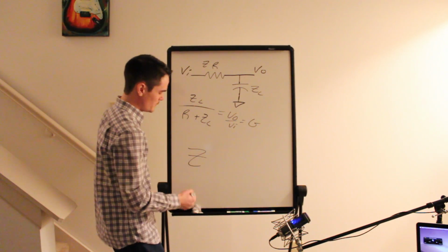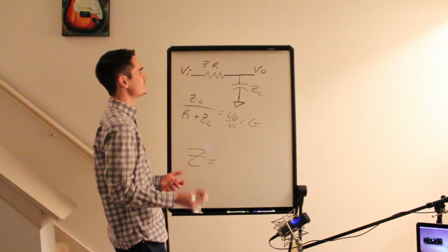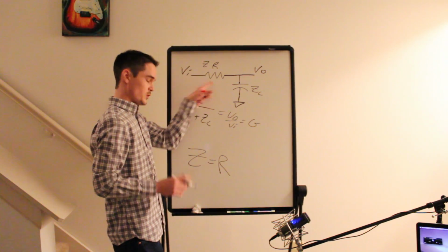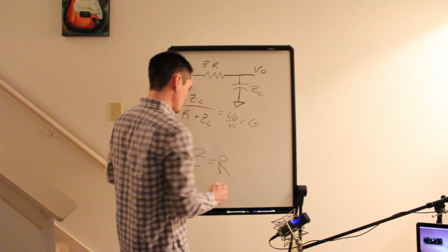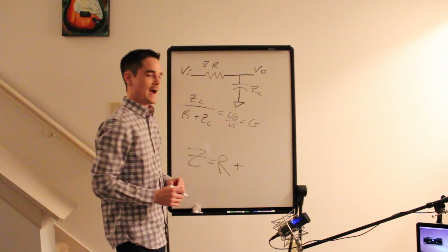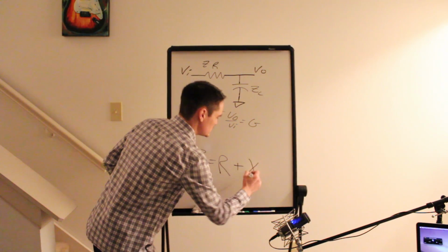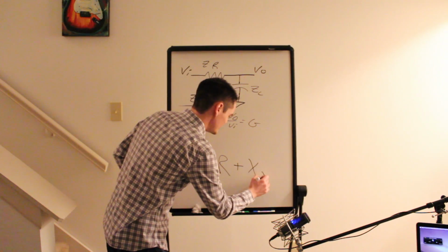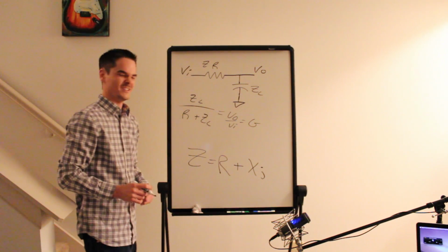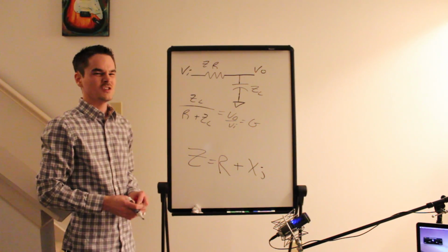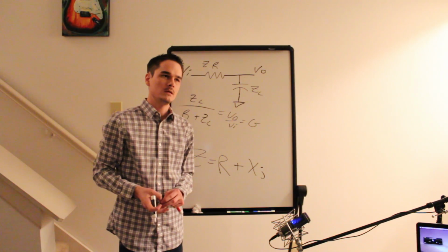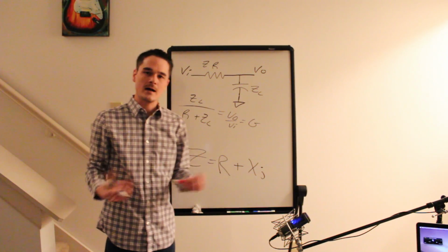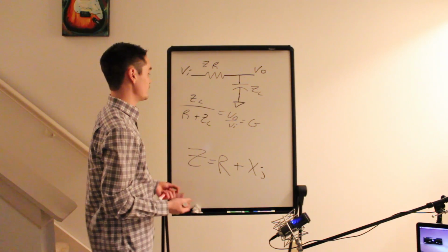So impedance generally is a complex number. That means it has a real part, which is purely resistance, and it's also made up of a reactance, X. But right next to X is this funny little thing called an imaginary number, J. Sometimes it's called I, but in electrical engineering we use J because I would be confusing, since we use I for current.